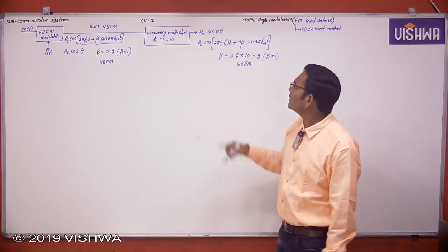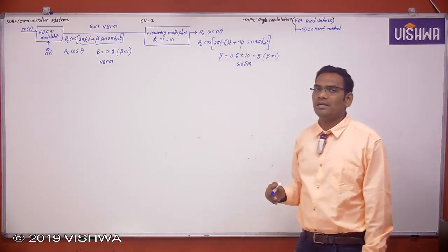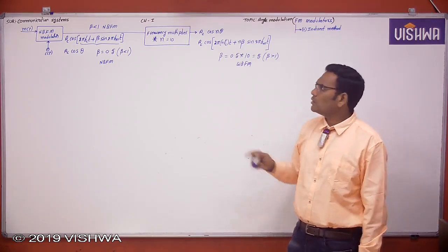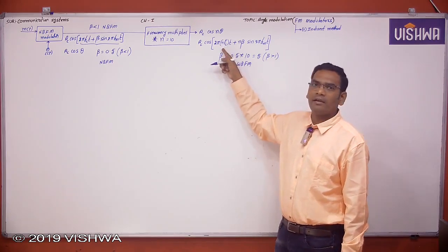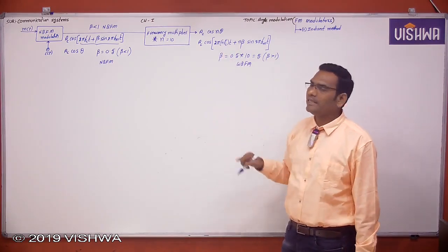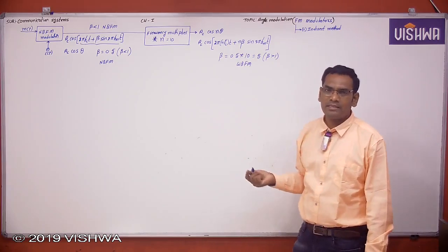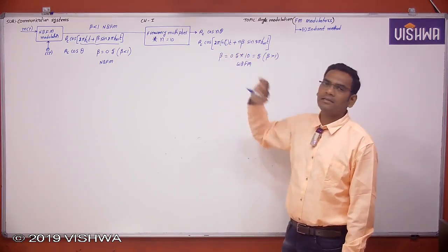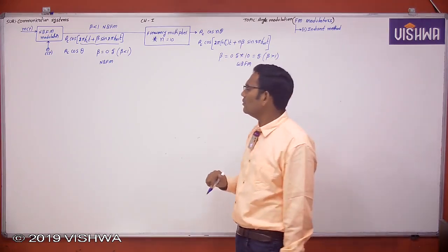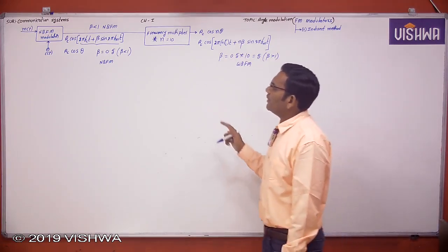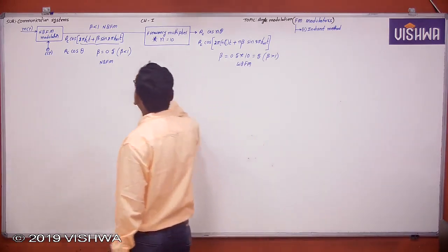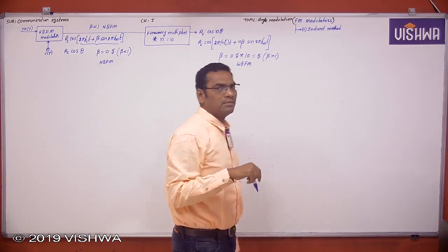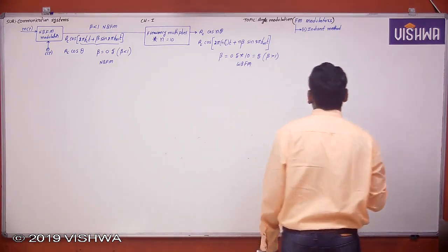But the students are asking, sir, the carrier frequency is also changing, but in FM the original carrier frequency should not change. Yes. Whatever the change by a factor of n times, you can decrease it again by using a mixer. The concept of a mixer is used to change the carrier frequency, and you can get back the original carrier frequency. In this way the narrow band FM signal is converted to wide band FM with the help of a frequency multiplier. This concept was given by a scientist called Armstrong.